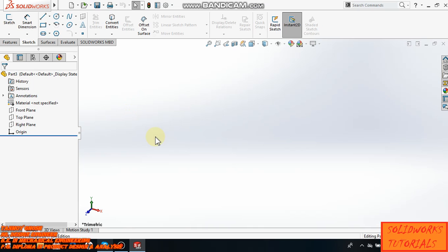For a 2D sketch, you need some plane or face where you can start your sketch. Solidworks gives you three default planes: front plane, top plane, and right plane. You should keep a few things in mind while creating and editing sketches. Sketches need to be clean and precise, with no gaps or overlaps and no stray sketch entities. It is best to keep each sketch simple. Complex sketches tend to fail or cause problems later.